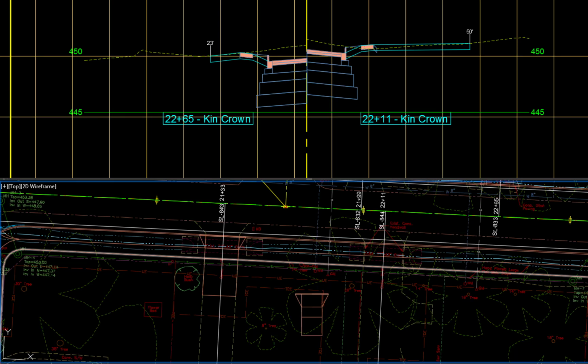All driveway profiles have been adjusted to reflect the length of the reconstruction work behind curb. The UCS coordinate system has been aligned with the Kincaid curb alignment. A driveway plan template has been copied to the vicinity of the right side driveway at station 22+11.